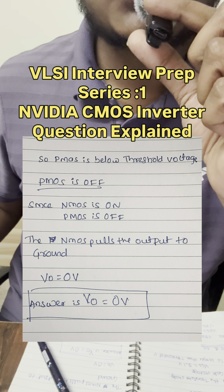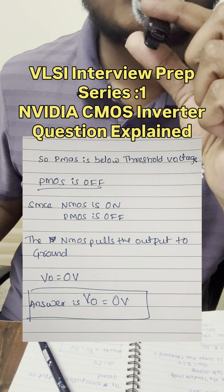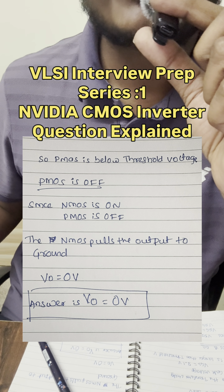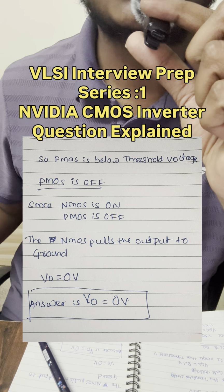Because the NMOS is on, it creates a conducting path between the output node and the ground, which pulls the output voltage down to ground. Since the PMOS is off, there is no path connecting the output to VDD. Therefore, the output node is pulled to ground through the NMOS transistor. Hence, the final output voltage of the inverter is 0 volts.